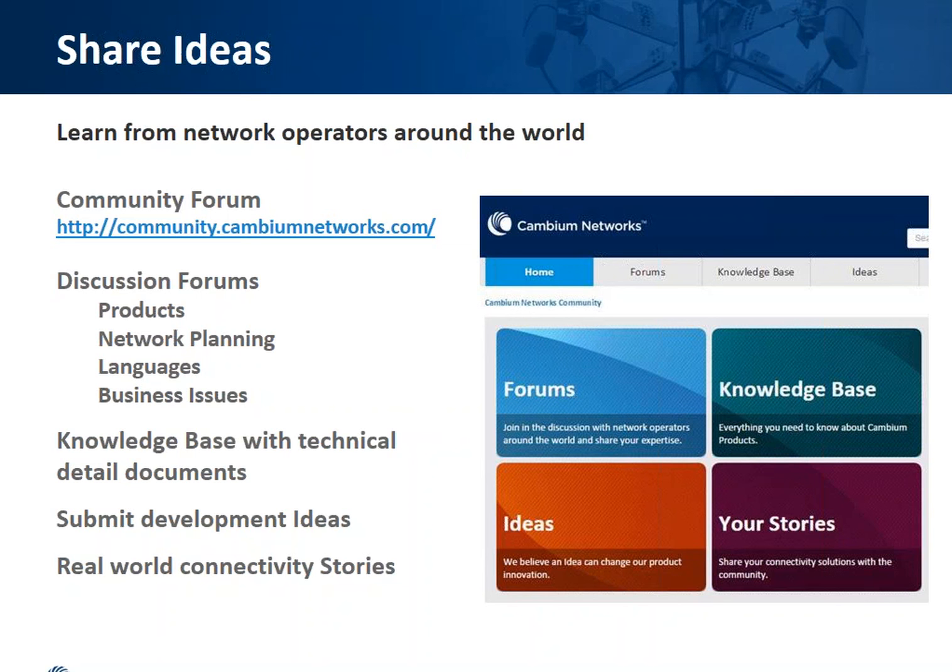Okay, we did have one question on side lobes of coverage areas. Can 90-degree sectors cover 360 degrees when you're very close in? Well, the sector antenna is actually a 65-degree, 3 dB roll-off. And typically, if you want maximum coverage, you would want to use 6 sectors to do that. We would otherwise recommend a 4-sector deployment to cover those 90-degree sectors, and within 3 miles, certainly that would be adequate. To do a 3-sector deployment, I think you're going to miss out on some of those in-between guys.